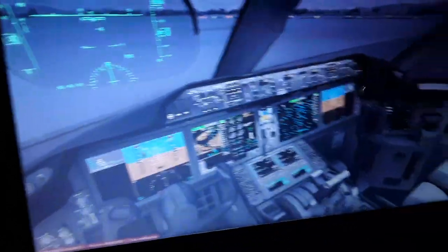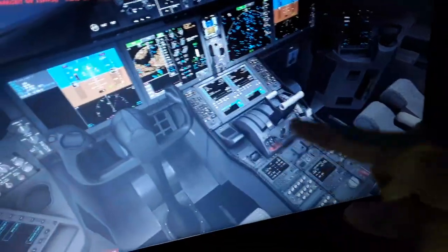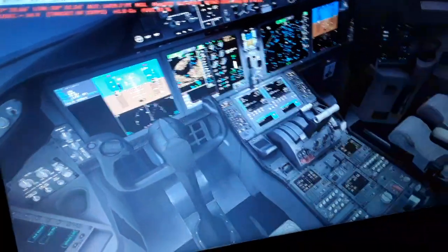A unique radio frequency we need to tune from the LSZH localizer over here, the radio management panel of this aircraft, automatically from the flight management computer in order to follow the LSZH localizer, the horizontal localizer, vertical glide slope, at the angle of approach for landing. I'm gonna show you also that.